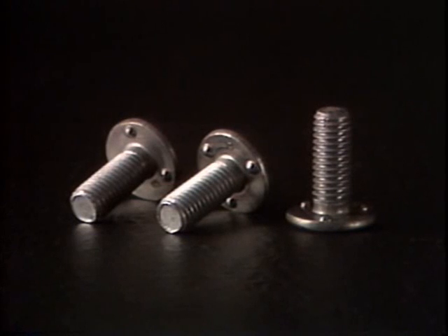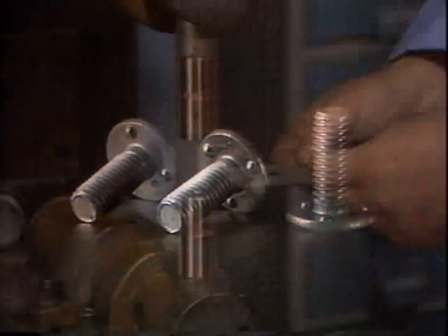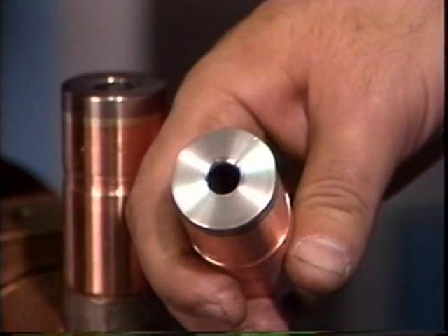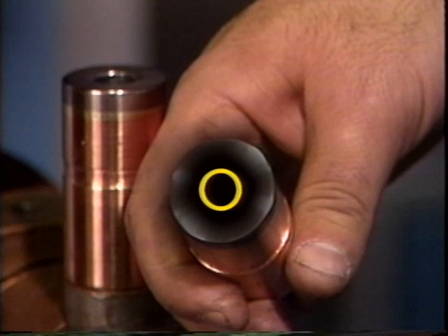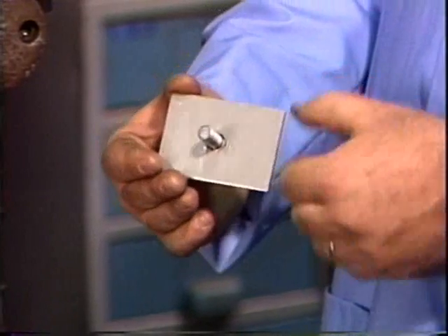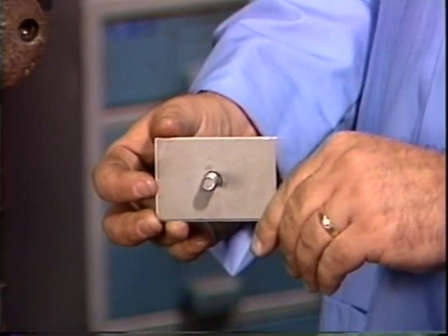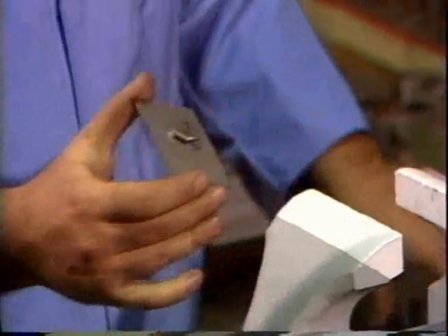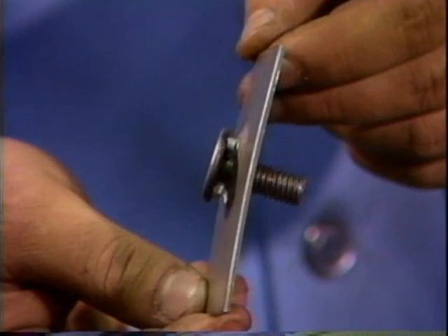Ohio's HW-style weld screw has 3 equal-size projections on a generous size head. Through-the-hole use allows self-location and eliminates any other fixturing. When threads extend through the sheet, an insulated lower electrode is essential. It will prevent the current from passing through the threaded portion of the fastener, resulting in current loss and damage to the thread. We are using an Ohio insulated lower electrode. As you will notice, there is very little marking on the underside of the test plate. In a destruct test, using a direct push against the welds, we will push slugs from the sheet.